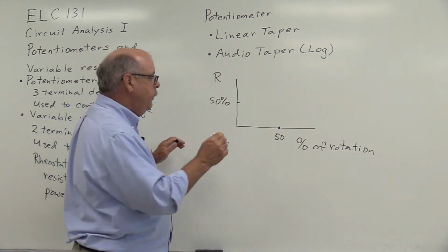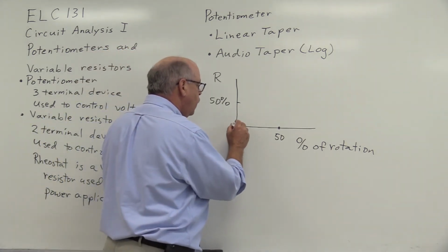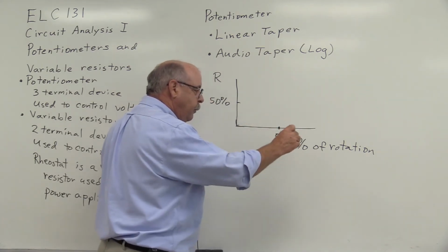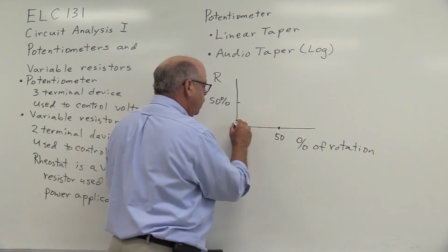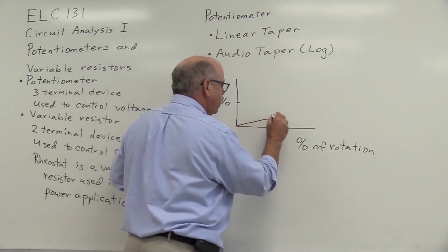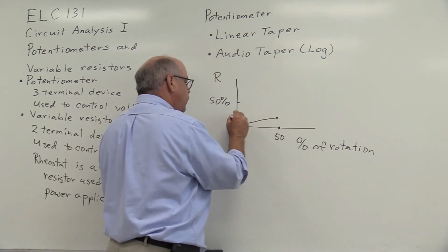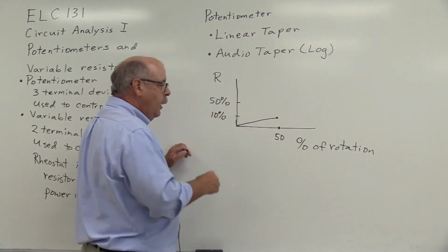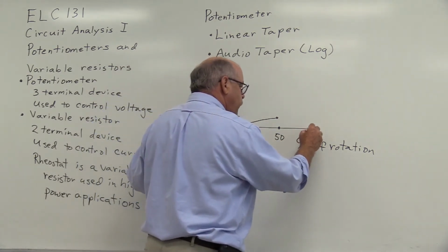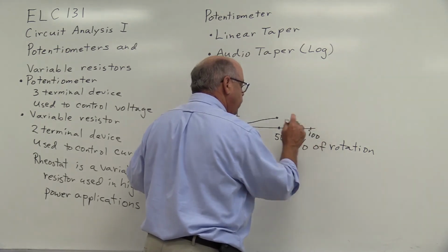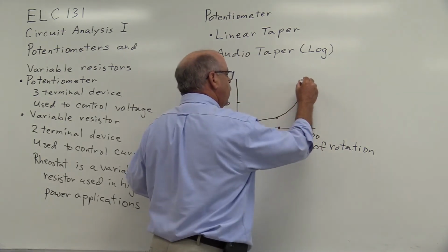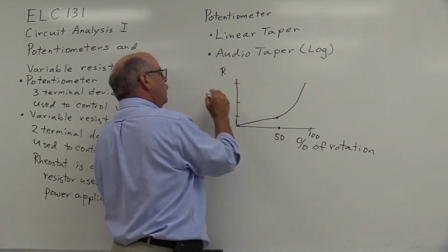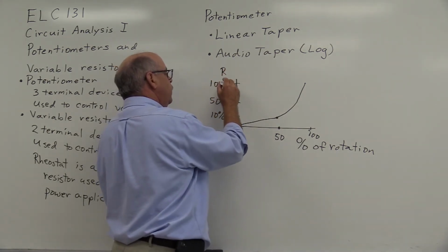So with the audio taper, at the 50% point of the rotation, the resistance only changes by about 10%. And then as we go to 100% of the rotation, the resistance goes all the way up to 100%.